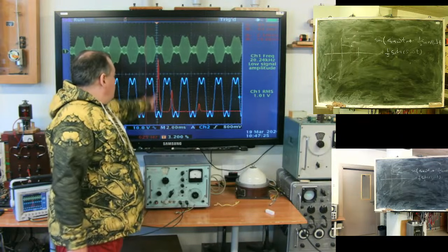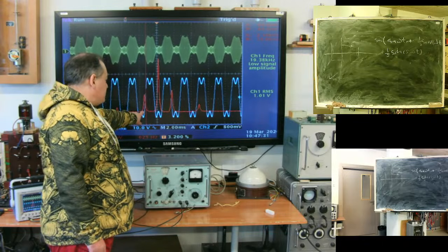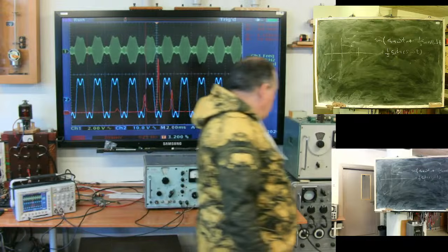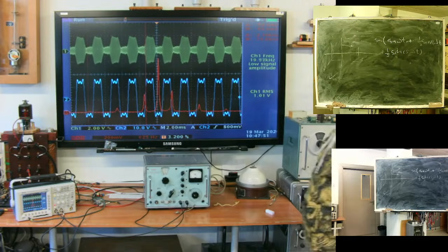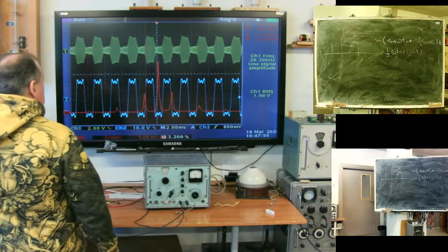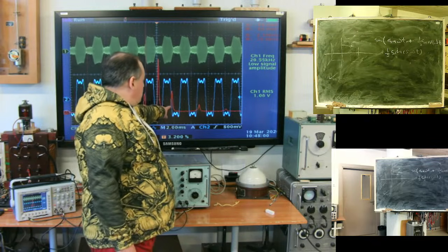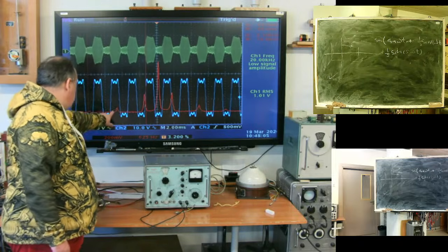And you see the carrier, base frequency of the signal, third harmonic plus, third harmonic minus. Add the fifth harmonic. Okay, here is my approximation to rectangular. Modulated signal, first harmonic, third, fifth. Minus base, minus third, minus fifth.